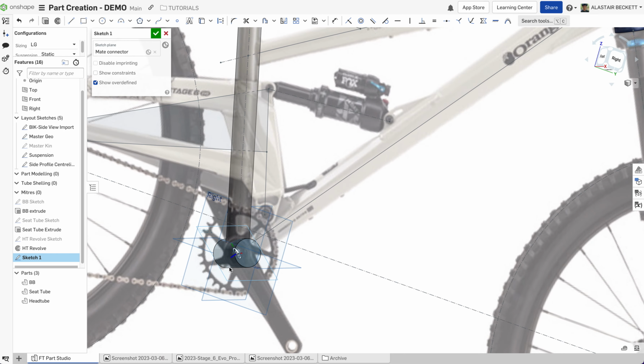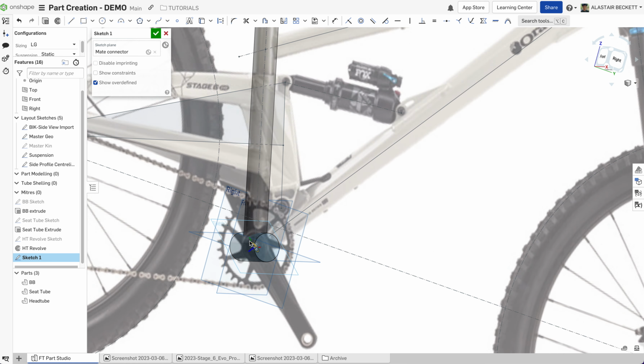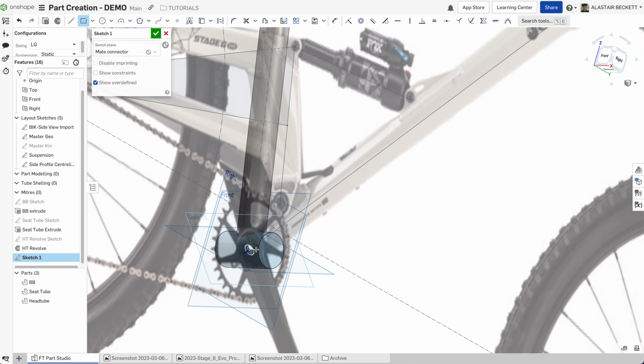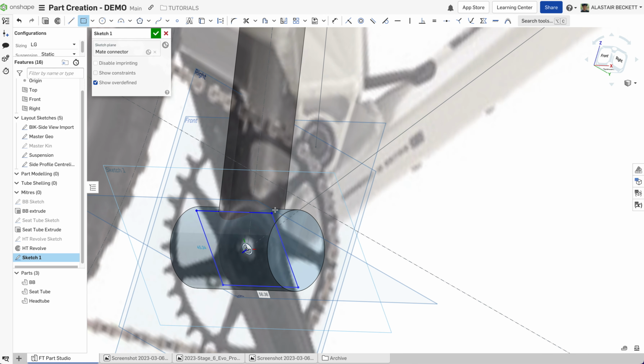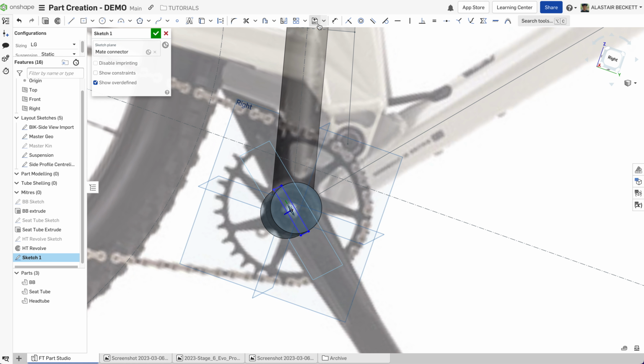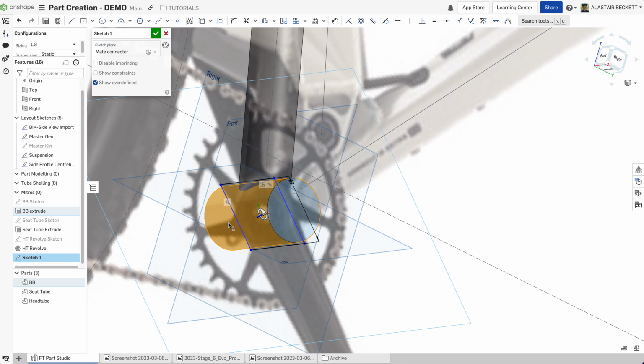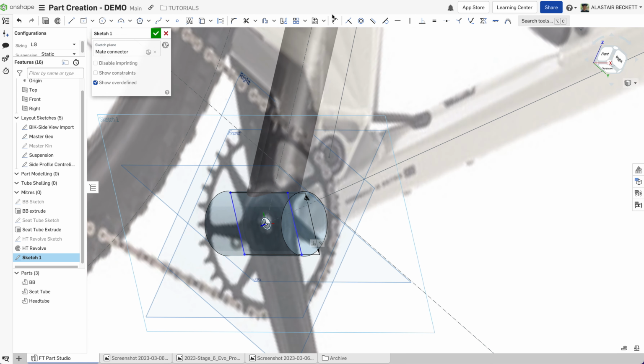So okay, where you want, let's say, I mean, this is not exact, obviously, based off what Orange bikes do, but let's start with a square or rectangle, and we'll round the edges. So in terms of height, we're going to want to see roughly where we think that might be. Let's have a guess at maybe 50 millimeters. Actually, we can base it off this, which is 44. Let's do that. So then we're not going to have any major overlap on our bottom bracket. And the width is, again, let's have a guess at 50 millimeters.